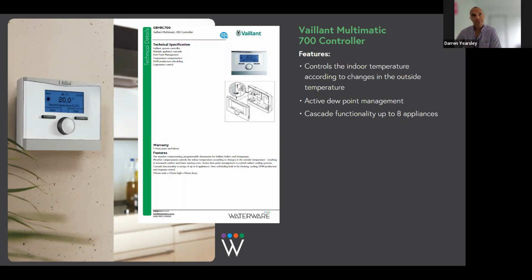The other advantage we have with this controller is this moving set point technology, where I can set a minimum acceptable set point at 55, dynamic boost at 70, and then Legionnaires at 60. All automatic, all run from the time clock. You can also connect the system for offsite monitoring, not maintenance. It'll send you automatic alerts if one of the heat pumps has an error. That functionality is all built in as well.